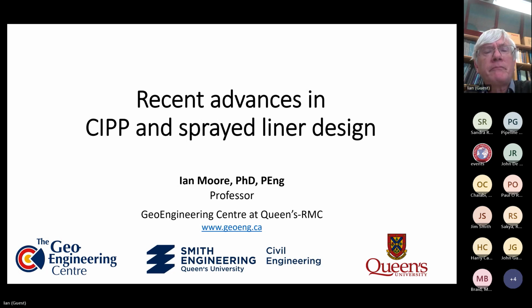Thanks, John. Excellent. And we have a question from Martin Long, who asks, was the potential bonding due to mechanical interlock at pipe joints when CIPP is inflated and cured considered as part of the assessment of friction bond between the liner and the host pipe, or is this not a concern? What a great question. I love that question.